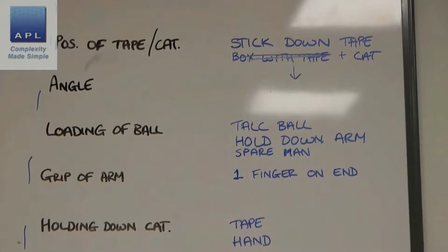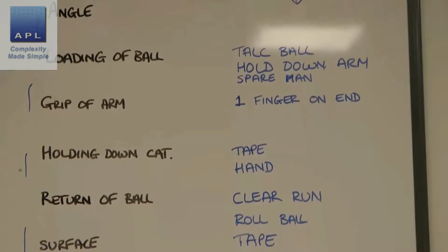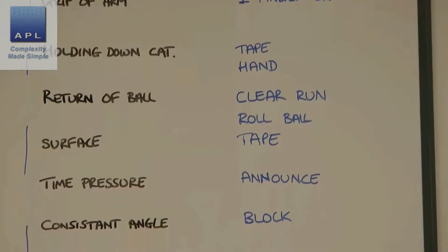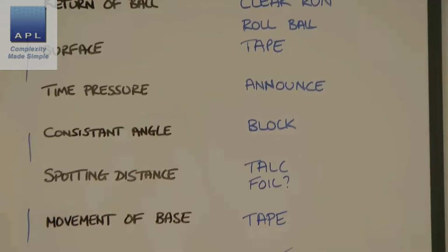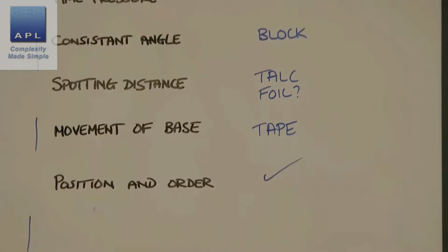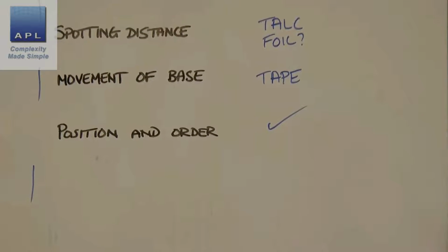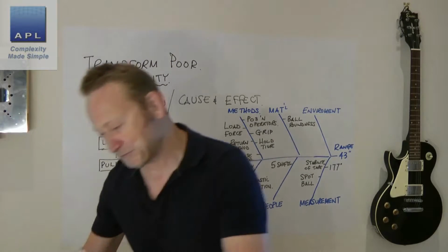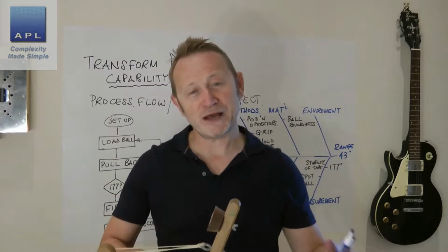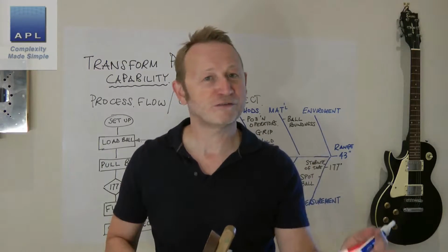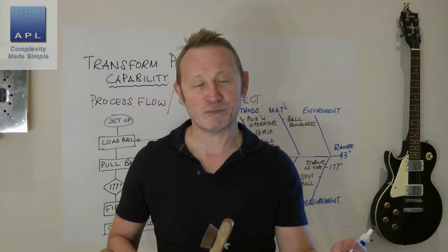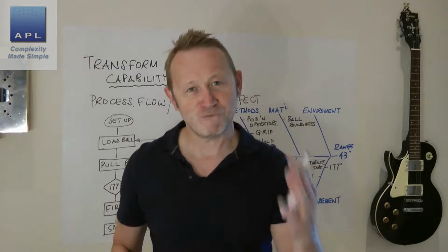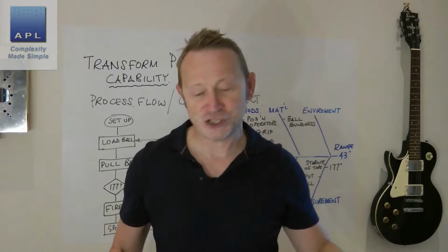Some of the solutions though, like the load force, all you can do is to come up with a good, specific, standard operating procedure for loading the ball. So it may be something like pull the arm back and then drop the ball in from about 10 millimeters above the cup. Very specific, very controlled, and then we teach that